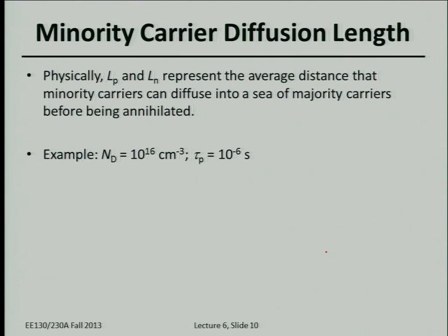So remember, in a previous lecture, we talked about a typical mean free path. That's the typical distance that an electron or a hole will travel before it gets scattered by the lattice vibration or by an ion, a Coulombic force. What was a mean free path? Do you remember? Just order of magnitude. Tens of nanometers. Very good. So let's see how long a diffusion length is. Let's say a typical doping concentration level is 10 to the 16 per centimeter cubed.